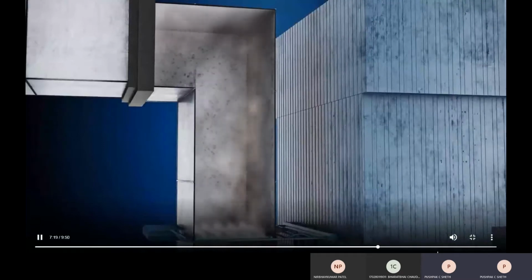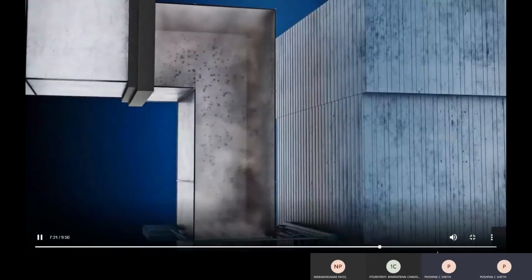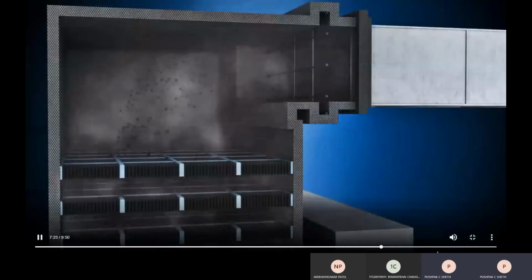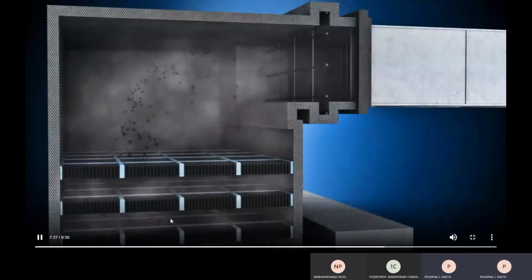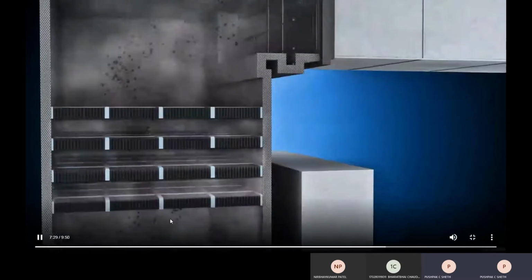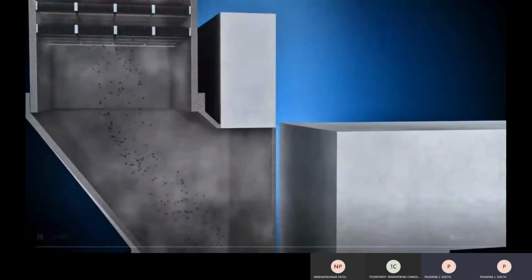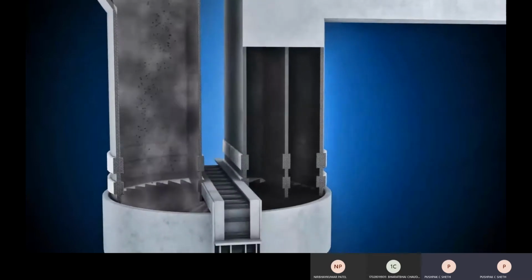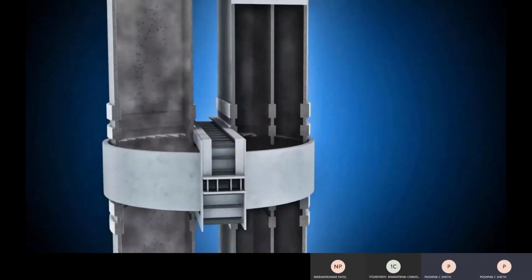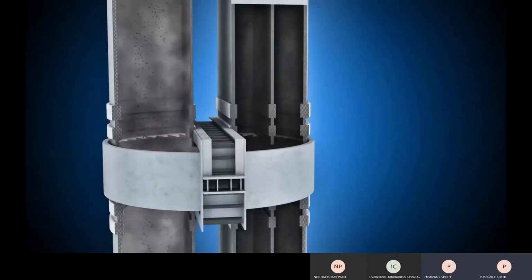While entering the SCR, ammonia is injected into the flue gas, where it reacts across several layers with the nitrogen oxide compounds. The exiting flue gas reheats the secondary air for the plant.